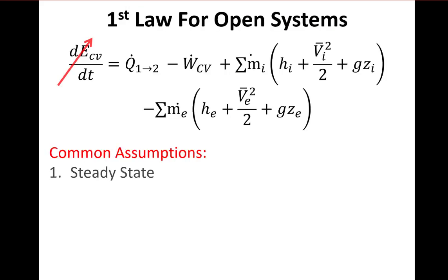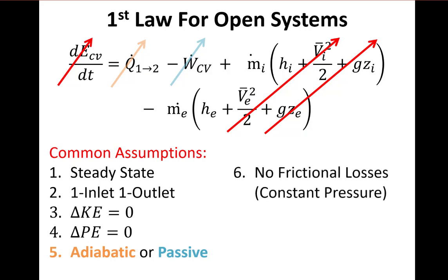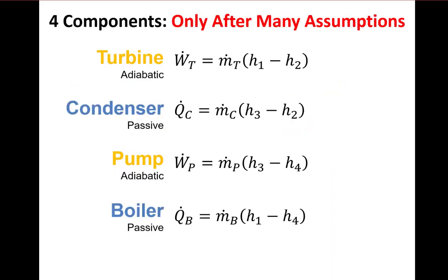If I do the first law, we're going to make some assumptions most of the time, although I could definitely make you relax some of these assumptions, the same assumptions we talked about before. What I end up getting in most cases, unless something funny happens, which I could do, is that the turbine and pump power are going to be m dot times h in minus h out, and the heat transfer rates on the hot side and the cold side, if you're solving for q dot, are going to be m dot times h out minus h in.